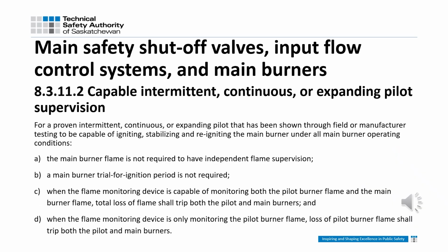8.3.11.2 CSA decided the existing definition of proved pilot should be modified to proven pilot because the existing definition only included proving the pilot before gas goes into the main burner. But it should be proving the pilot throughout the pilot burner operation. This resulted in updating a few clauses using the new term proven.